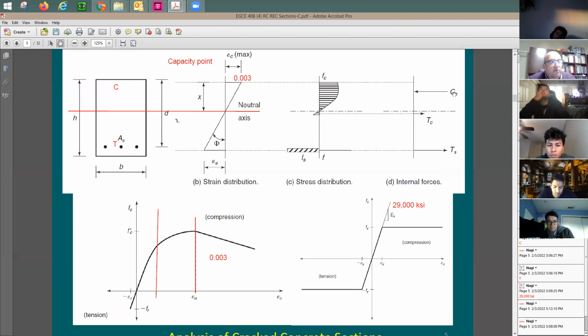If you remember, we said the compression of the concrete here is going to be equal to the volume of the stress distribution over this rectangular section. Meaning I need someone to figure out the volume of this weird shape. Someone's going to say, this is going to be tough. How about the centroid? Where is this compression force located? Where is the centroid of this shape? I know when you have a rectangular shape, it's going to be in the middle. A triangular distribution is going to be at the top 1/3. But for this, what should I do? I'm going to say nothing.